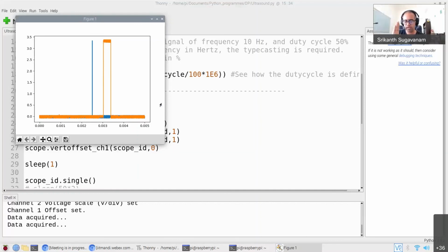Every time I inquire it, what will happen is because the Raspberry Pi is also a computer, and because the computer also has an operating system, some operations of the operating system take precedence over the operations that you want to do. So it might happen that you want to fire the ultrasound sensor. You are trying to send a signal to it, but it gets slightly delayed. So you think that it's happening every 0.5 seconds, but it might be happening at every 0.8 seconds or even 1 second. So you cannot assign a particular time to it.